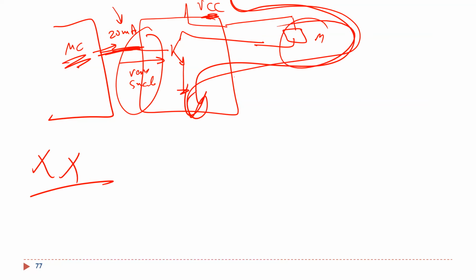So you are gonna have this problem for sure in your capstone or something like that. Again, the problem is the microcontroller. Usually, when you want to interface a device that needs too much current, the microcontroller is not able to give you this current. You have to put a circuit in the middle. This circuit has several names.